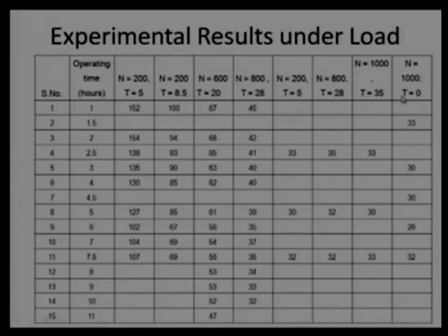Now, what is happening? Why does vibration not happen at 1000 rpm? We can say there are a number of asperities which were earlier there, and they have completely got flattened or torn away or removed from the surface, and there is some marginal lubrication now coming. We say that there is a fluid film lubrication with some boundary lubrication. There is some percentage of boundary lubrication and a major percentage of full film lubrication. That is why the gear wear rate is low in this situation. That is a favorable situation for us.